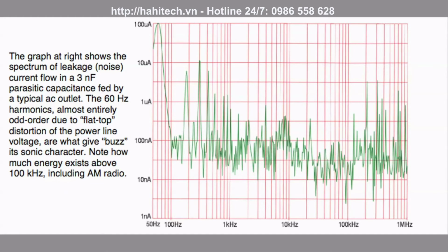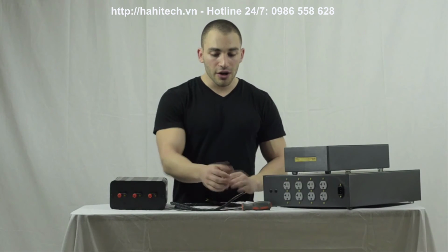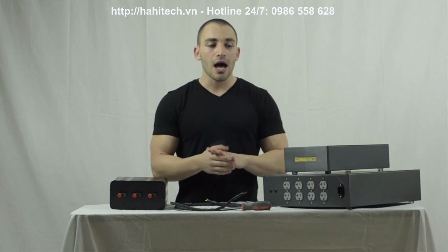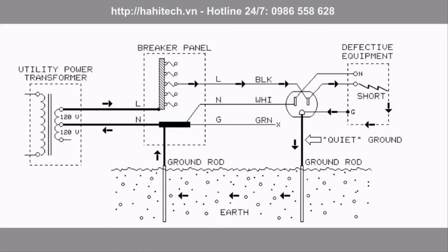The other misconception that I have seen is a lot of audiophiles think, okay, I need a dedicated ground for my audio system that's separate from the rest of my house. And so they install a ground rod for their system. The biggest issue with using a separate ground rod for your audio system is the same thing I talked about in terms of these receptacles.